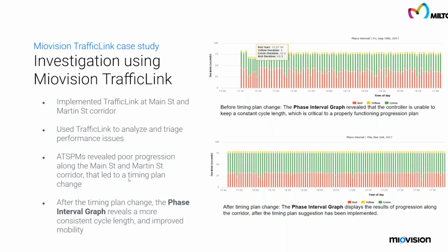From there, we looked at the detection design, the performance measures, the signal operation and the overall volumes coming through here. And like many small, tight corridors, especially when signals are really tight together, coordination is incredibly important, and offsets are incredibly important, especially within, call it, a 500-foot range. In this type of range, coordination was our first spot to look, because how well are these coordinated?